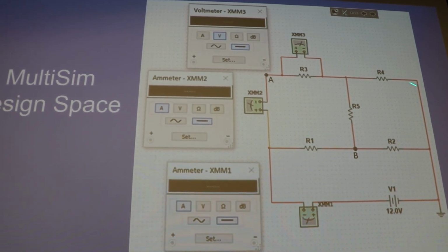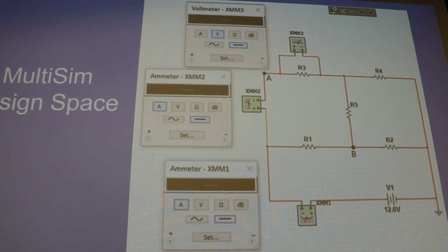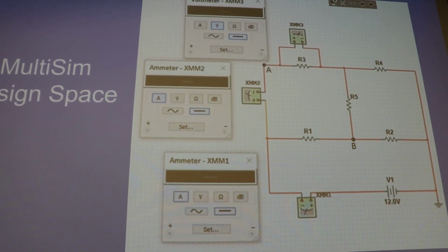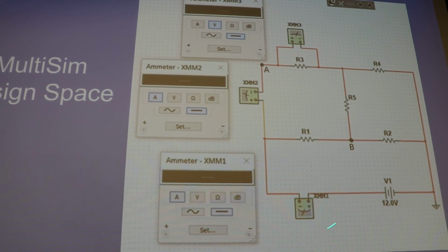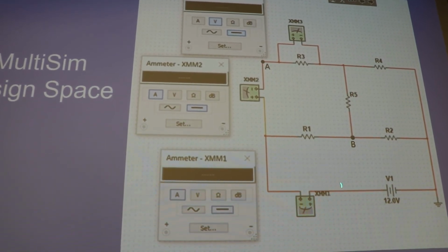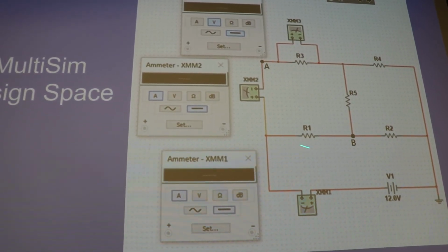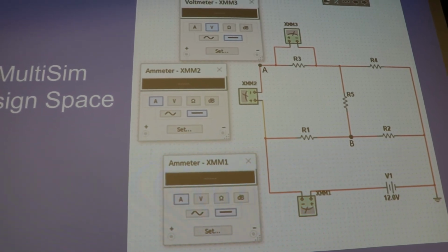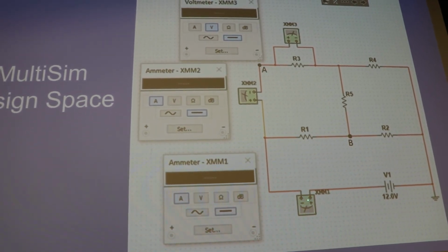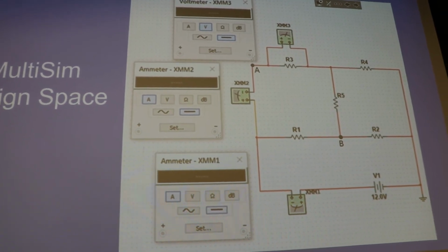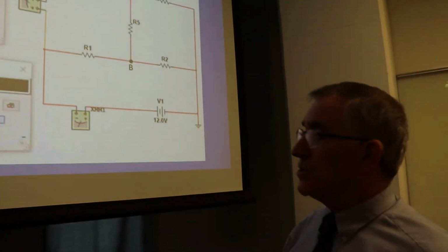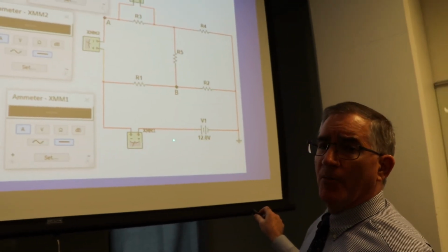And that'll be going to these 5 resistors that are your REQ, your equivalent resistance. All right? That'll be your equivalent resistance. So much current will come out of the battery depending on how much resistance is out here. So you'll do 10 measurements, just measuring the current right here and setting the voltage right there. Now remember to give your voltage like 3 sig figs. You can give it 4. Don't give it much more than that.